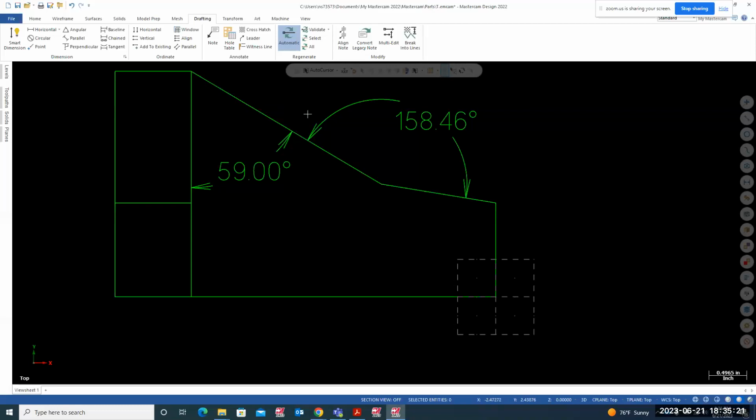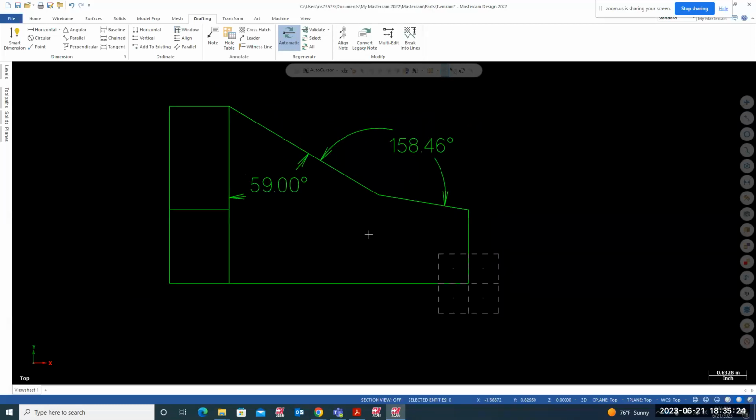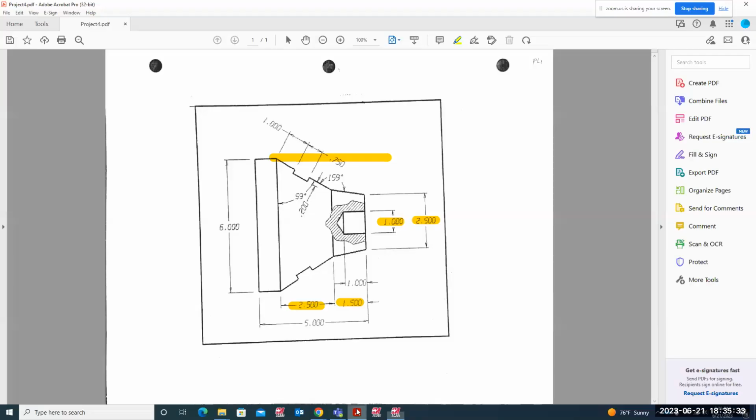And there's a groove right here. This is something I want you guys to try. Do this groove, this guy right there. See this groove right there? I want you guys to do that. So we're going to talk about this toolpath once we meet next week, on this part. We're going to go with center drill, and we're going to cut that groove at an angle. To cut a groove at an angle, you have to have an angle tool, set it up on the machine at that angle, and then you can cut that.